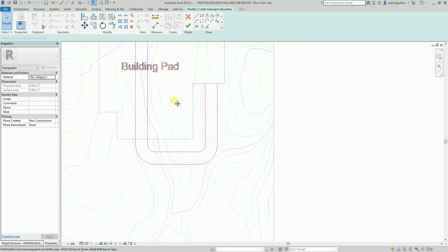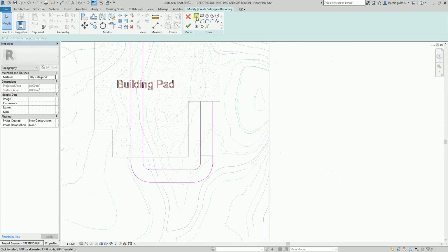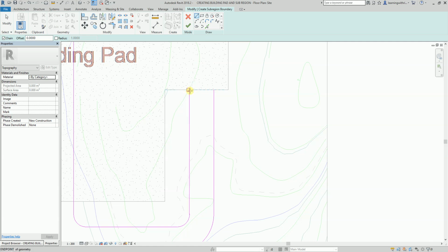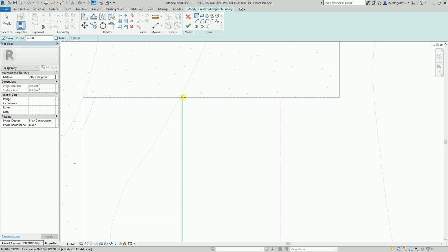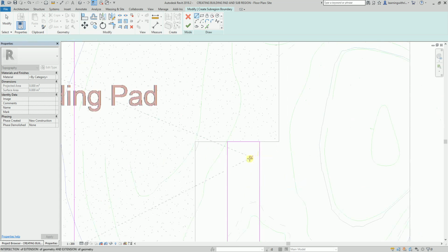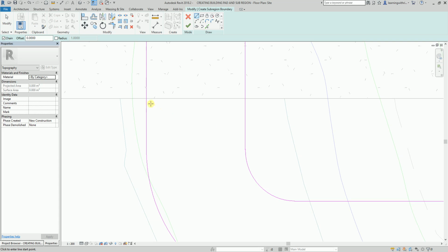Now, like what I have said, it should be closed, no intersection, no overlapping. So I'll create a line just to close these lines. There you go. Escape. I'll close this also. One, two, close. Then after that, I just need to trim to clean the corners.